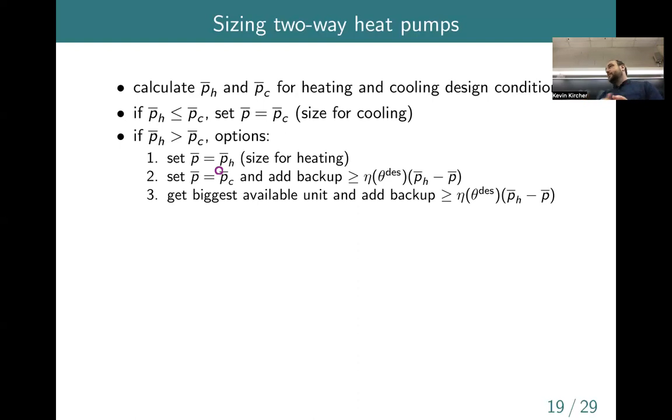What you would like is for it to run smoothly and steadily for longer periods. Part of that is just because every time you spin up rotating machinery, you have to overcome inertia and friction and stuff like that, so there's some energy penalty to doing that. If you're doing it more and more often, then you get less and less efficient.